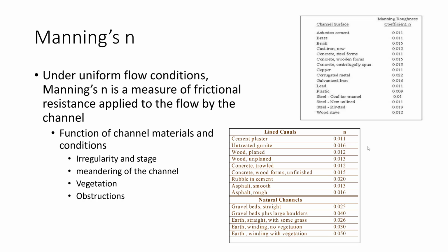Typically, during engineering design, we go to tables such as the ones I show here and pick a typical value of Manning's coefficient and use that in our design calculations. But what we're going to do in today's lab is actually measure this Manning's coefficient in an open channel.